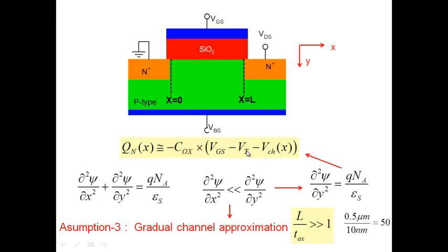And your equation for current, for example, the familiar current in saturation going as (VGS minus VT) squared, none of that would be valid. It will not behave like the transistor that you're familiar with if this condition is not true. The transistor characteristics are well saturated, and it behaves in the familiar form, only if this condition is true.